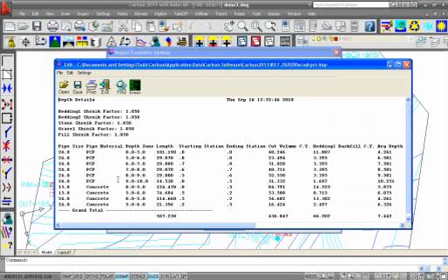Now what we have is a report showing the pipe size, 24, and pipe material, and the depth and the linear footage of those pipe types at those materials. So 24-inch PCP, there's 100 feet of that between 0 and 5 feet deep. If I had 24-inch of concrete, I would see the length on that as well. So I can see the linear footage of all those things broken out.